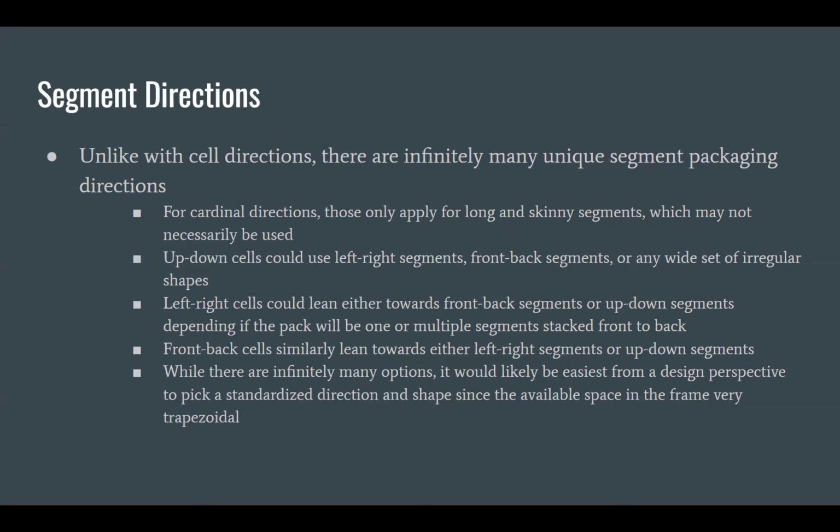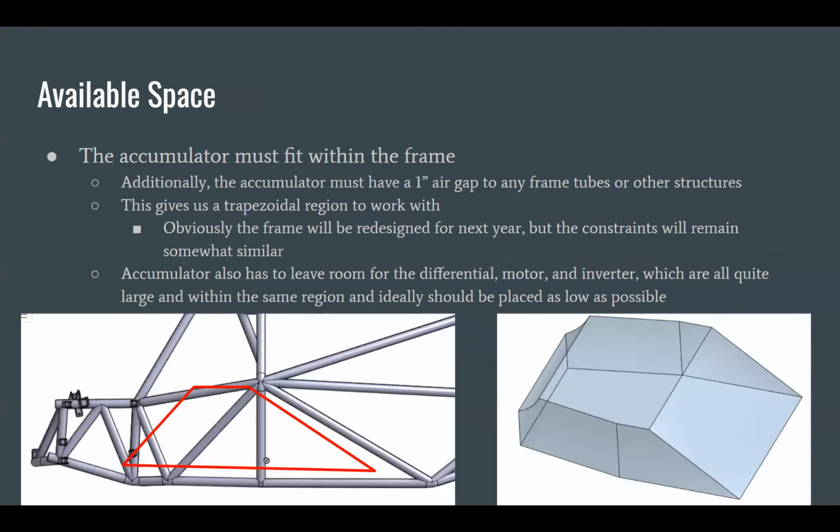But if you put them in series, you just don't have to worry about that. So the general practice is that your segments will be connected in series. I am unaware of any teams recently that run parallel configurations. Every team I've seen puts their cells in parallel in the segment and then runs series. But in theory, you could do a parallel configuration. In theory, you could make an e-box for every individual cell. Have 560 segments.